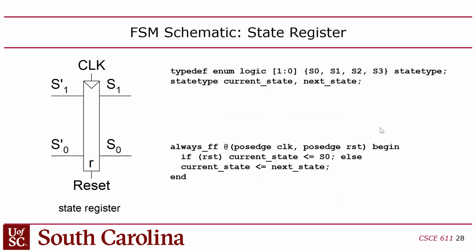Okay, so in Verilog then, that was the Boolean algebra implementation I showed you. When you do a state machine in SystemVerilog, this is actually specific to SystemVerilog. In regular Verilog, you have to choose your own state encodings manually. But in SystemVerilog, you can create an enumerated type for the state. That's what I did up there. I have typedef enum logic [1:0]. You still have to give the number of bits for this enumerated type, so I said it's a 2-bit signal, but I gave it actual symbolic values that can go there. And I call it state_type.